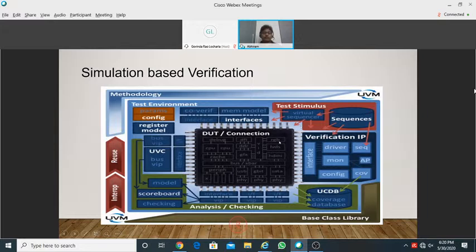And also for doing this complex verification, we know that every SOC has a lot of registers. So all the registers will be defined in some industry standard specification called IP-XACT. Now, all the models will be integrated into this model called the register model. So now you have your register model, which has all the register descriptions of all your IPs in a SOC.